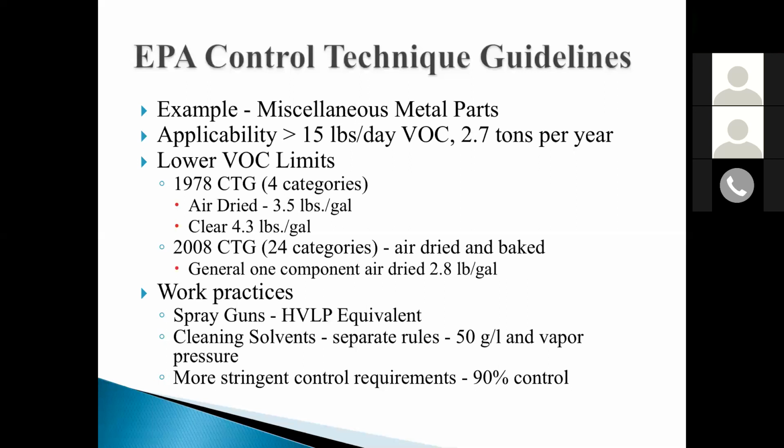It has a lot to do with polymerization, but there is confusion because people might start off with the starting point, and then just assume all of it's being liberated, and don't fully understand that any of it is going to be bound up in the coating material, the coating solid. Or the other way is that it may say X VOC content, but actually it is going to liberate some VOCs. It could go both ways.